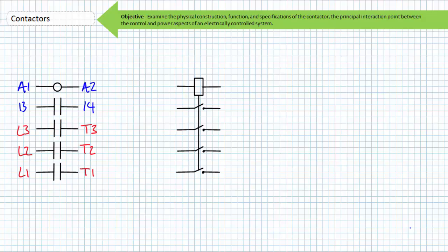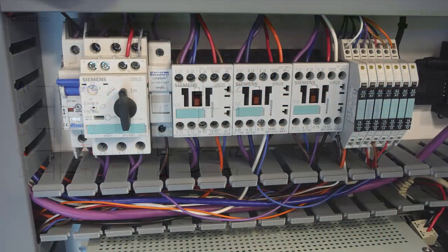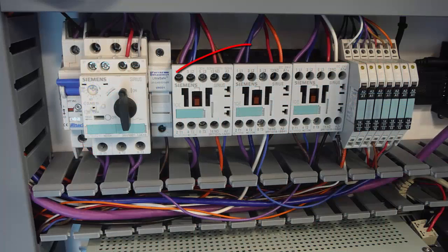This is the IEC schematic symbol for a contactor. You can kind of see the similarities. This is the coil. The IEC schematic symbol makes it very clear the power contacts are controlled by the mechanical interlock with the coil. This is the normally open auxiliary contact, and these are the line and load terminals for the power contacts. Contactors are often permanently mounted in an electrical cabinet. Hardwired connections to the terminals are sometimes hidden inside plastic channels.